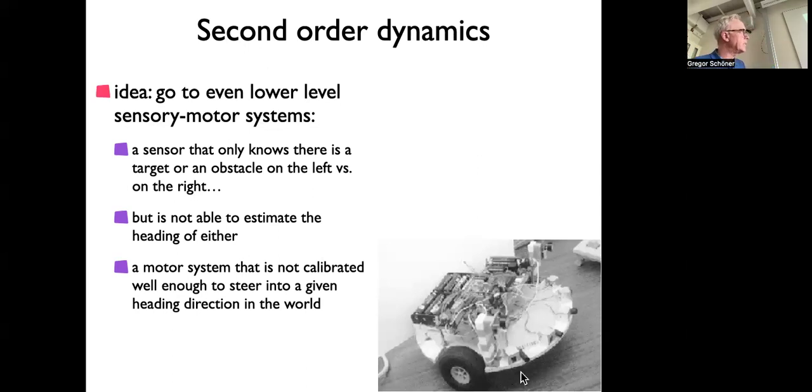You don't see that. It has these same kind of sensors. This black thing is the emitter of infrared light, and this little cube here is the detector. And the black thing is actually a rubber we put on top to control the spread of that infrared light. When you do this, you have to address these different sensors in sequence, because only one can be on at a time, since the reflected light causes crosstalk among the sensors. So that's actually the limitation on how fast the sensing is, because you have to have a little window for every sensor to take a reading.